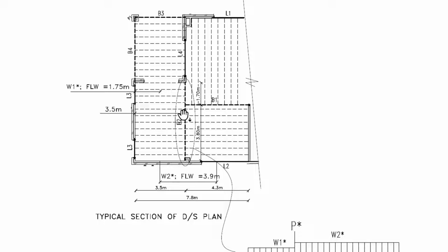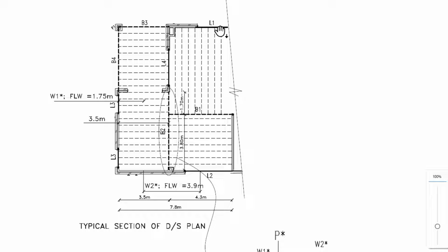The dashed line represents the direction of the floor joists. As you can see here, the floor joists going left to right of the page are supported by beam B2, B4, lintels L3 and L4, and then we have the floor joists going up and down the page, and they are supported by beam B1 and lintel L1. And of course, the reactions at the end of B1 are then transferred to beam B2 and the internal wall on the other side.